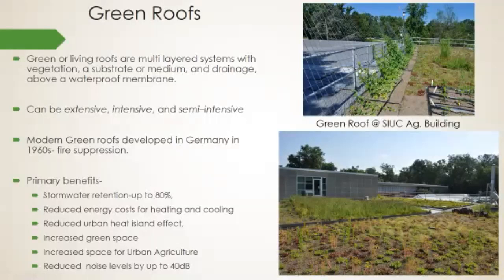insulation. They have a big impact on the urban heat island effect. So they increase the amount of evapotranspiration, so they're kind of air conditioning in urban areas, and unvegetated roofs tend to have a lower albedo. So the lower an albedo is, the albedo effect, that means it's absorbing more heat. So concrete has a pretty low albedo, and a lot of that heat is going to be absorbed by those materials, not as much bouncing off.